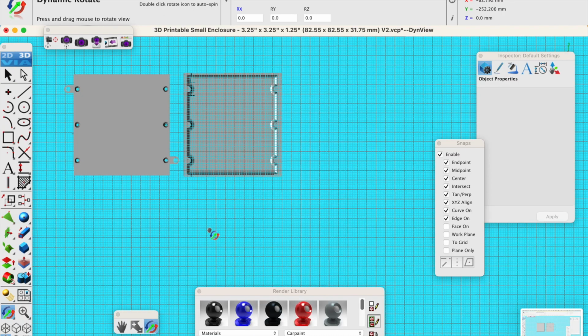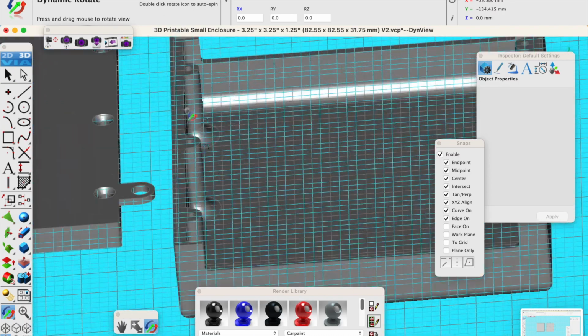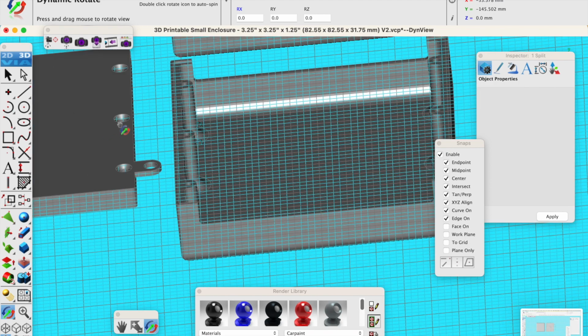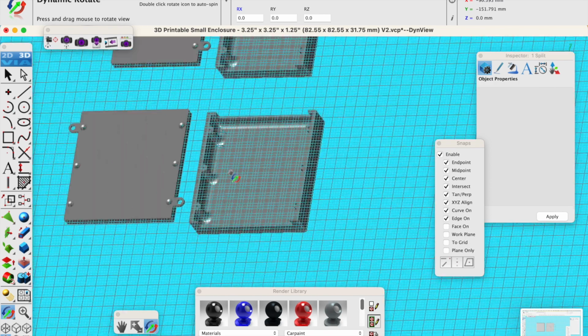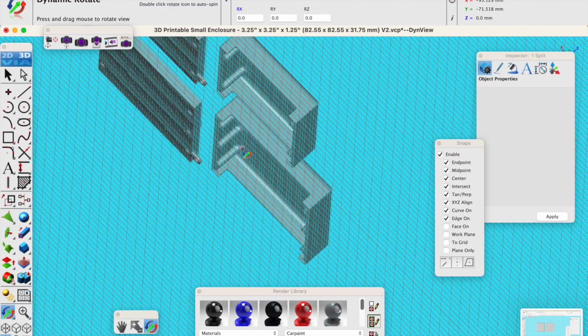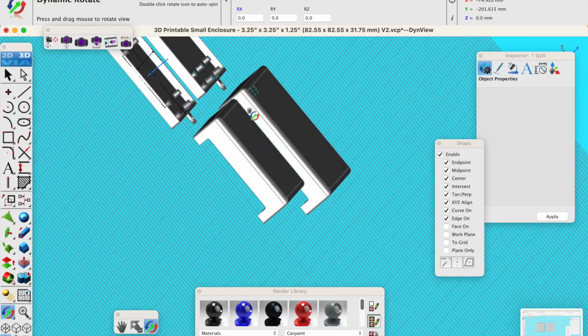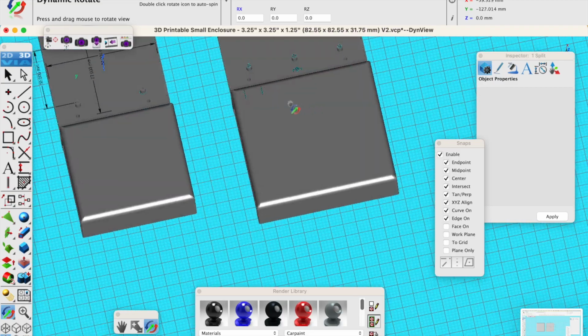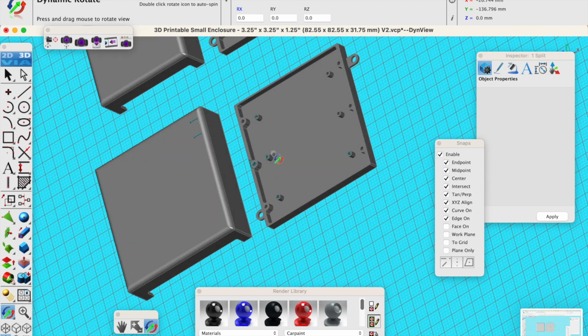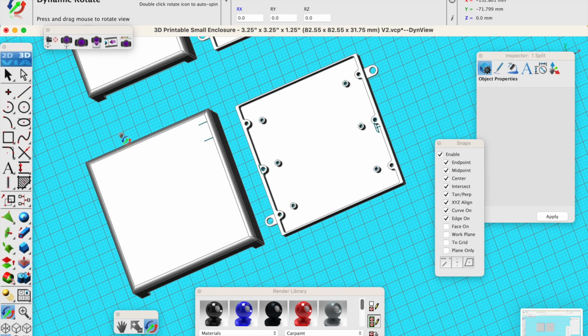All right. It has the hole there for the pass-through bolt or pass-through machine screw. I like the height of these because the relays fit nicely under the cover. There's no need to make it any larger. What I want to do though is I want to put one more boss right here in the center because these PCBs tend to flex. But I'm going to show you a different way to do it this time.